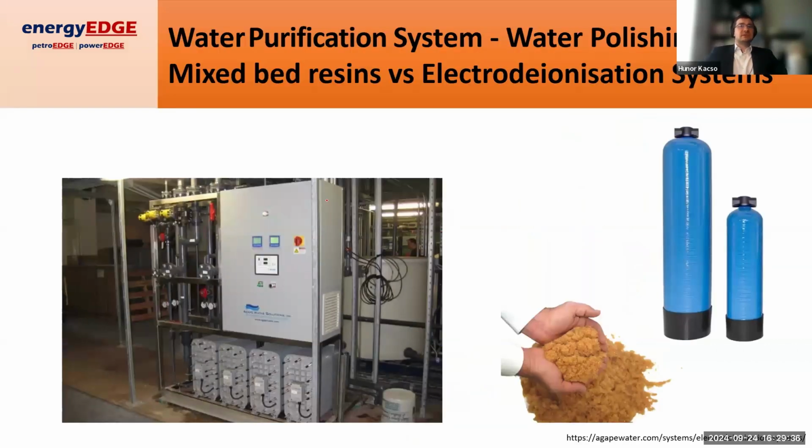Okay, so the water polishing can be done in two ways. And this is a relatively recent development in the PEM electrolyzer sphere. What a lot of electrolyzer OEMs have been looking at is, of course, DI resin, which is what we've been using for a long time. You can also regenerate DI resins, but that has not been done in PEM electrolysis. Not that a lot of companies haven't looked at regenerating the DI resin catalyst, but it hasn't really been done in PEM electrolysis to this point.